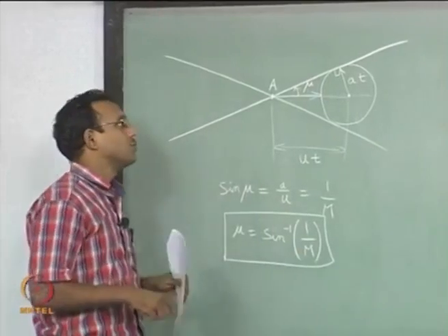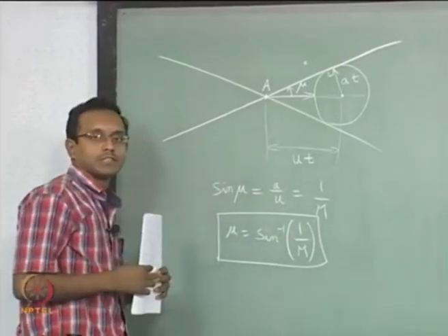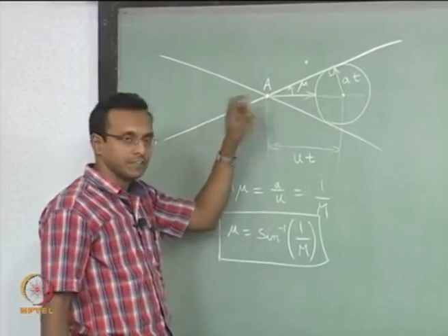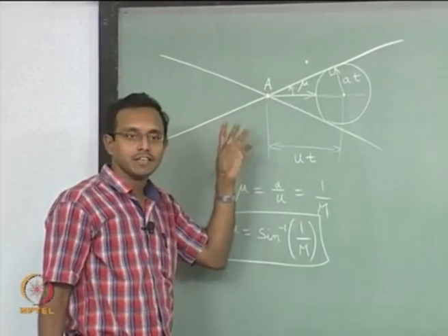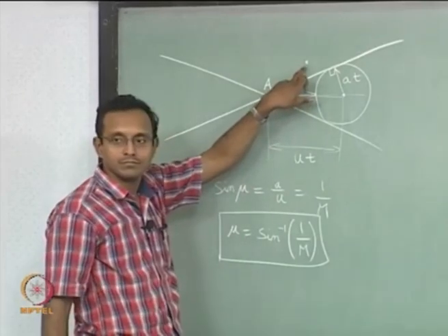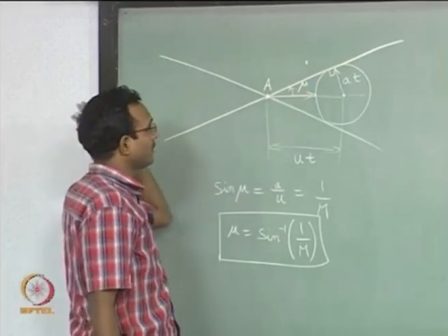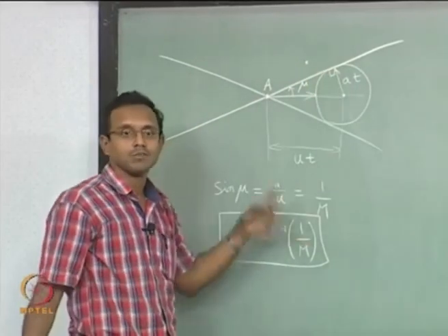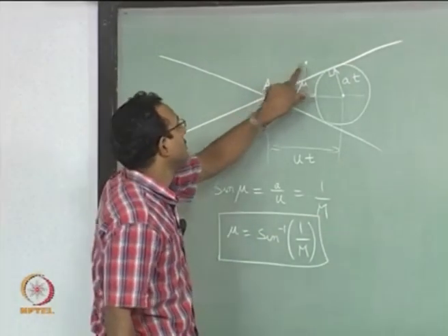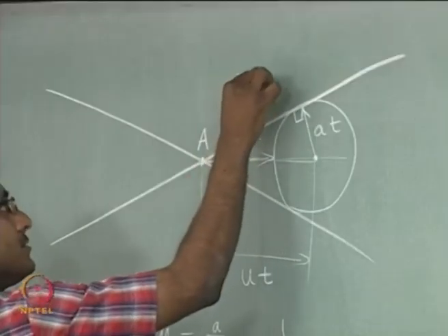Now, we already said that the information never reaches this particular point outside there. That says that if this point wants to affect some change in the flow field somewhere, that information can never reach this point, even if I wait for long enough time, because the fluid is going to be pushing the waves out this way. No wave is going to reach this point, and because of that, I can tell that this region can be called the zone of silence.